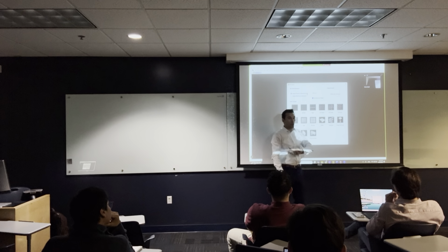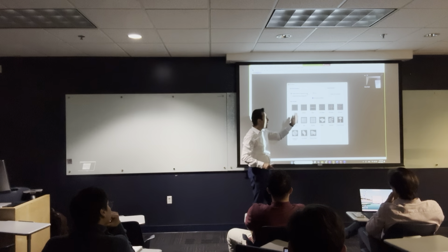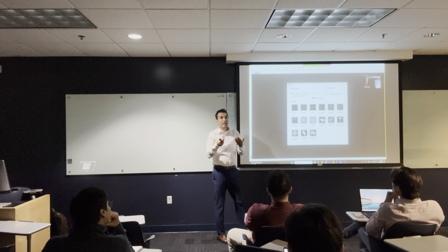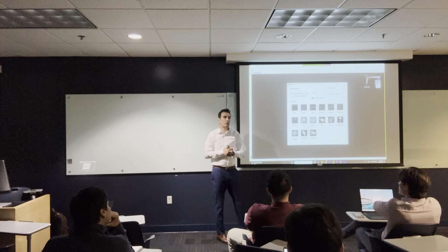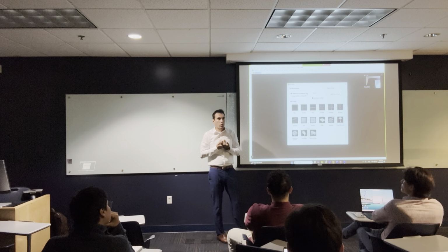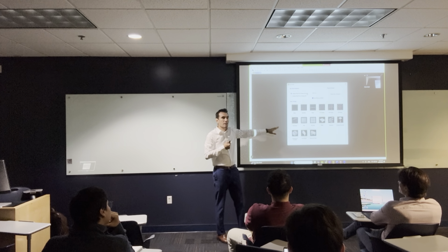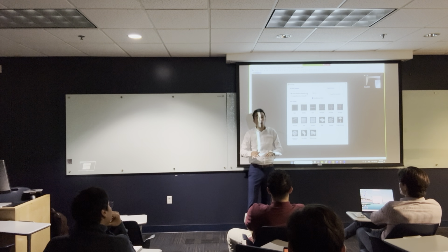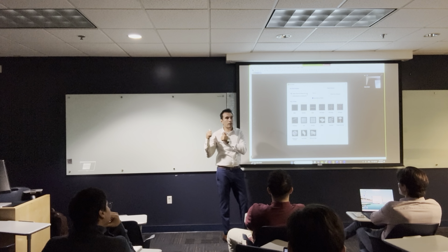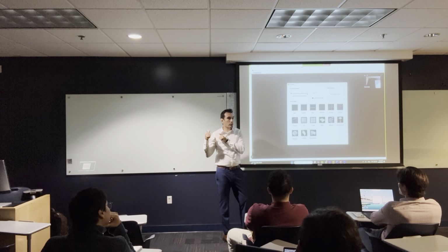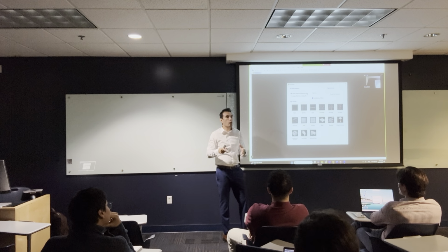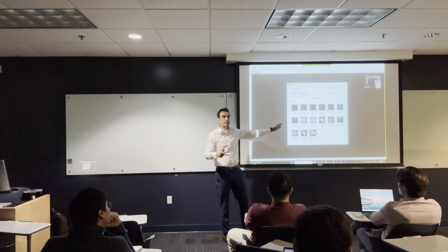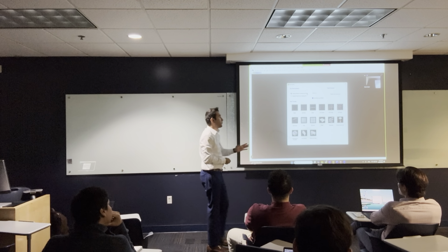If I have a stair or a spiral stair, I would do SAP 2000. Till now, if I get any of these projects, I would use SAP 2000 for that. But if I got a tall building project, I forget about SAP 2000. It's not good for tall building projects. I would do ETABS, and that's actually what we use in most of the design firms. Most of the tall buildings that are out there are done by ETABS, not SAP 2000.